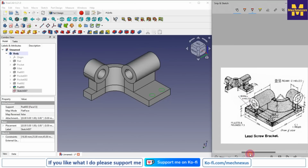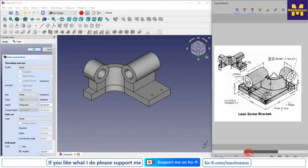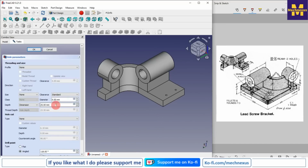Either we can use the cut tool or we can use the hole tool. So here we will use the hole tool. Let me adjust my image in the center. So here it is a drill of 19 mm, so I will give my diameter 19.